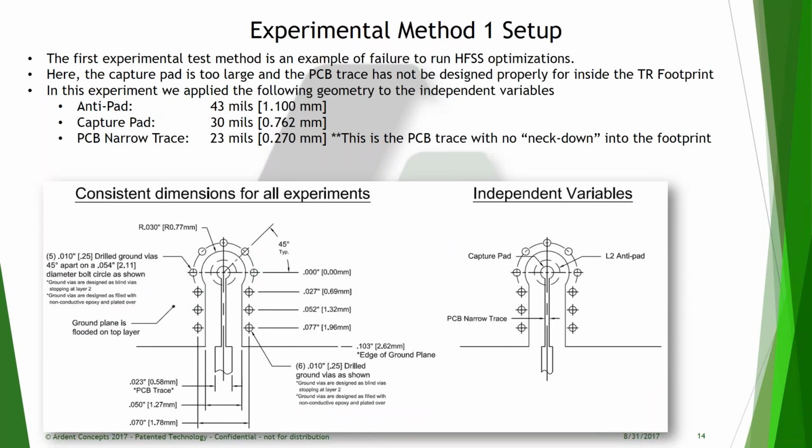Experimental method number 1 setup. Now, what we did with this experiment was we decided to keep the anti-pad on L2 the same, but we made the capture pad a little larger than normal. And the real big thing that we did here is we kept the same PCB trace from outside the footprint, and we ran it right into the capture pad.